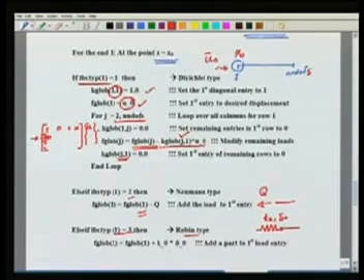Okay. So we will take care first of this part, that is, the total force due to this end will be in this direction k naught delta naught minus u naught. So this part is a known, this part is an unknown. Okay. So the known part we are going to add to the load vector side, that is f glob 1 becomes f glob 1 plus k naught delta naught, because it is a compressive force, remember that.